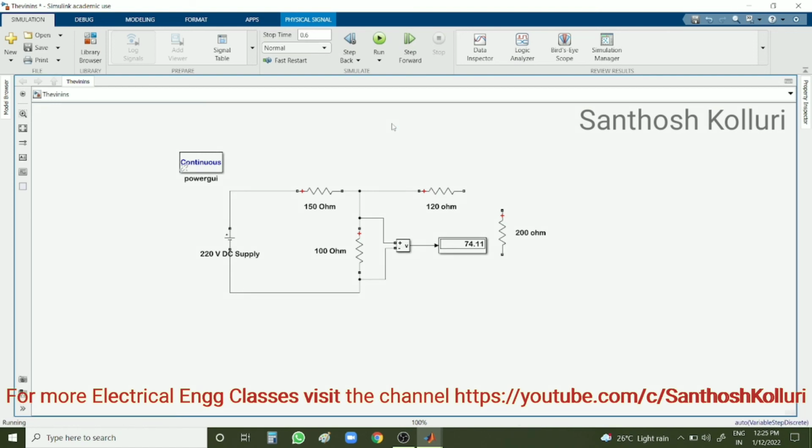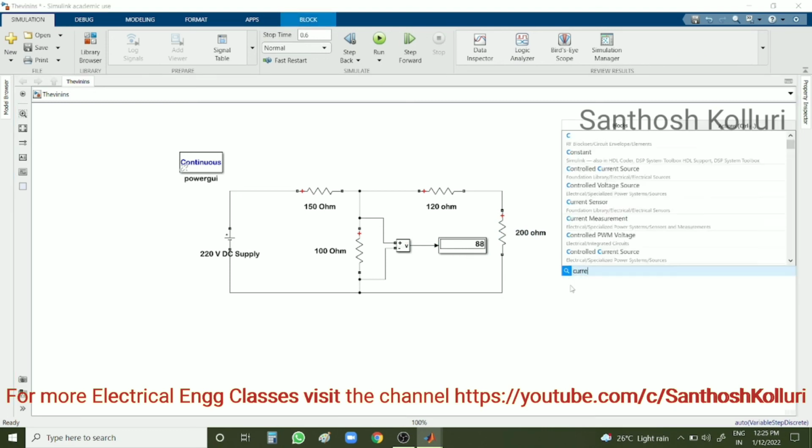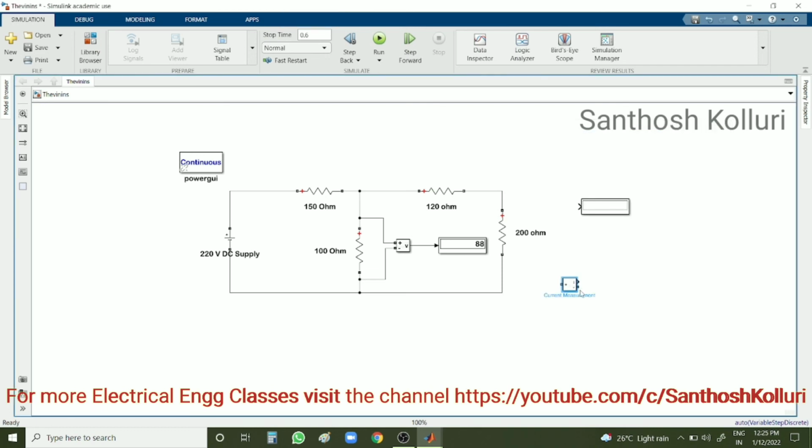Run the simulation for 0.6 seconds. Then note down the reading of Thevenin's voltage and compare with the theoretical value. To calculate the load current, take a current measurement block and connect it in series with the 200 ohms. Then run the simulation. Now we are able to calculate the load current.